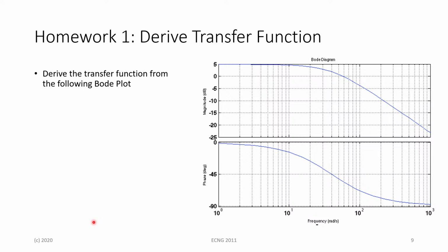So, for this particular Bode plot that we see here, instead of starting at the 0 decibel line, it's going to start at the 5 decibel line instead. And we also know that if we take -3 of that 5, that's going to be at 2 decibels. We can obtain where this actual pole lies as such.